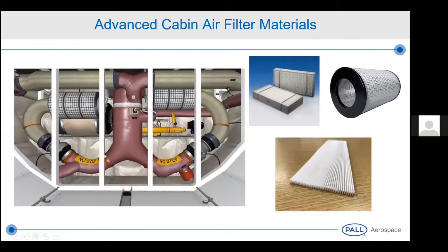The two filters on top, you see there are cylindrical filters typical for A319, A321 type of architecture. We see the two recirculation fans, and on the top of the mixing chamber, we see the distribution ducts. So there are 5 distribution ducts in total. The 2 that you can see on the top of the mixing chamber are feeding the forward cabin.